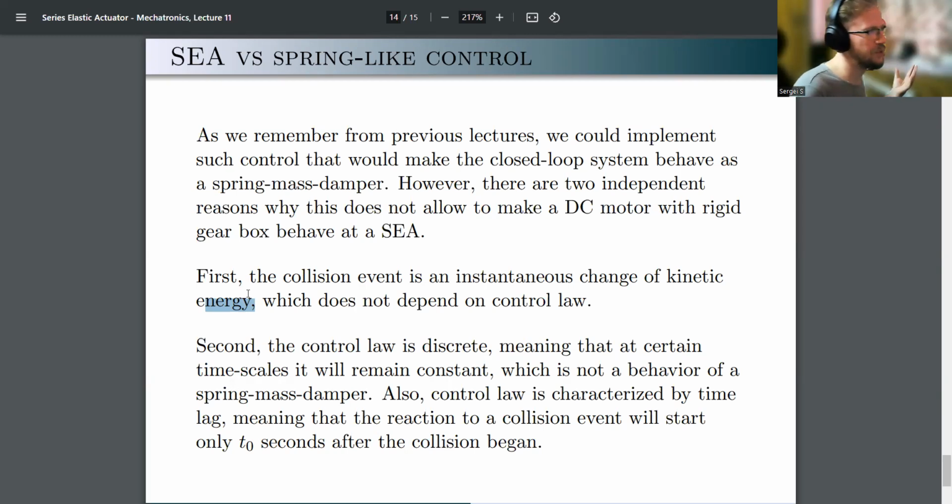It's going to be very simple, and this would allow us to avoid destruction because it's going to be rigid and robust. So it's not like we avoid collisions entirely. We just avoid collisions in the places which are vulnerable, such as gearboxes, the DC motor itself, and all those small bearings and so on. All right, so this is the first reason.